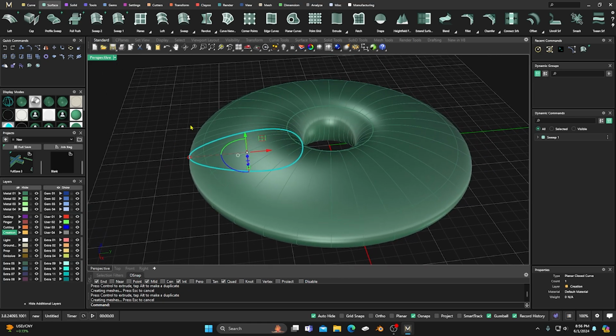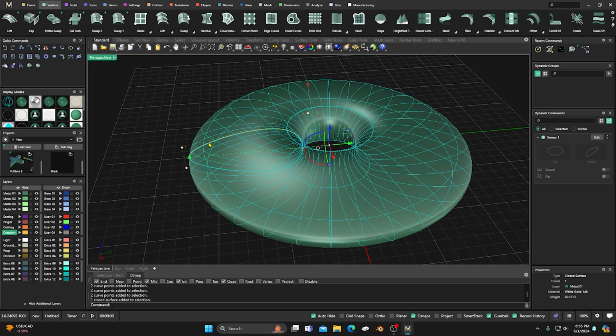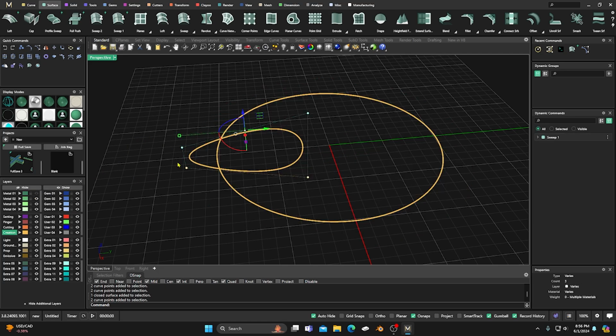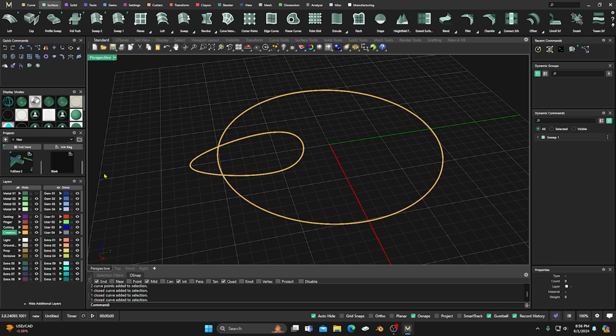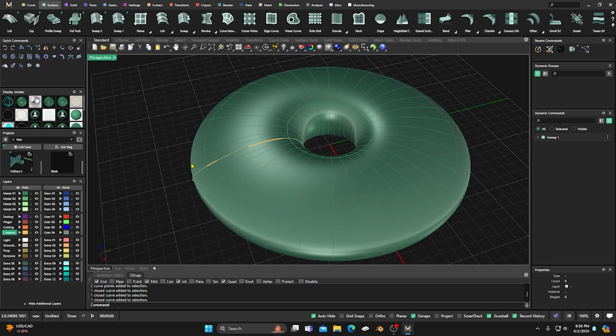One thing I should mention, if I go to turn on the points, right, I can still select my curve. Well, I can still select the curve, maybe. Supposed to be able to. Yeah, I can still select the curve inside MatrixGold, but if you're still using M9, you will not be able to select your curve when your points are on. You'll have to turn your points off, and then you can select your curve. Okay, just FYI. Let's turn that surface back on, because we'll get going.